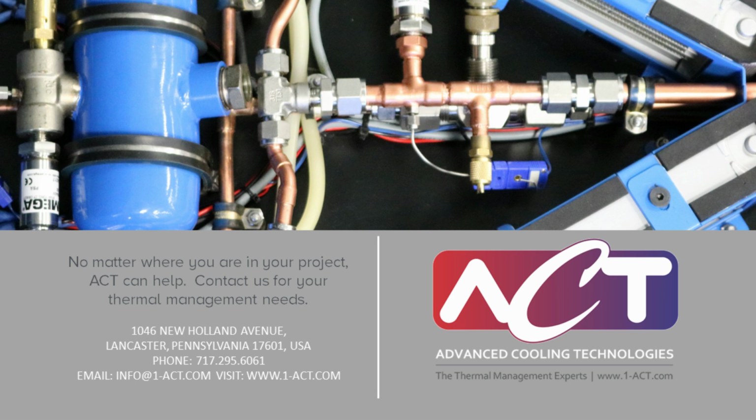Very good question. In terms of how much additional volume should be considered, we generally recommend anywhere between 10 to 15%, just based on the expansion as it goes from a solid state to a liquid state. Since I'm fairly conservative, I would say just outright assume 15%. And with your design, you can assume that we're going to get some additional PCM in there that you hadn't previously anticipated, which tends to be a good thing.